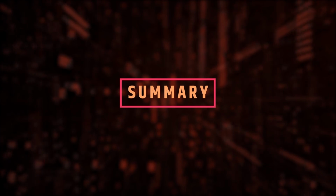Now, it is time to wind up the session. Let us have a quick recap. Registers were introduced in this session, which is a sequential circuit containing flip-flops in a cascaded manner. We discussed the left and right shift registers and also the different modes of entering data to and exiting data from the registers. And in detail, we discussed SISO and SIPO registers.